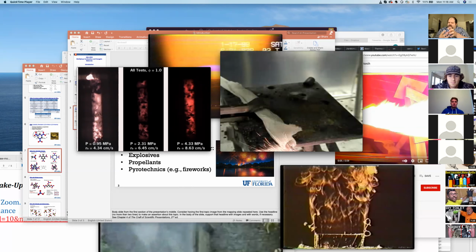And then those hot combustion products are heating up the black powder on the outside and basically preheating it. And so the flame accelerates once it gets into here because of that convective heating effect. And that's why this is called convective burning. Typically in rocket and combustion systems, you avoid this very, very much because this can cause explosions.